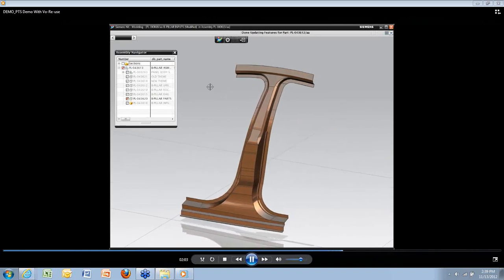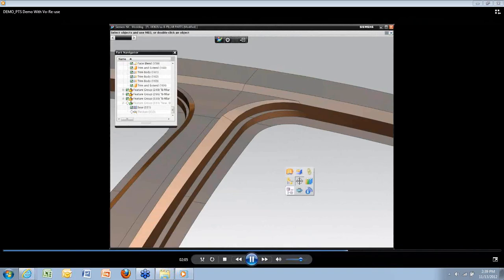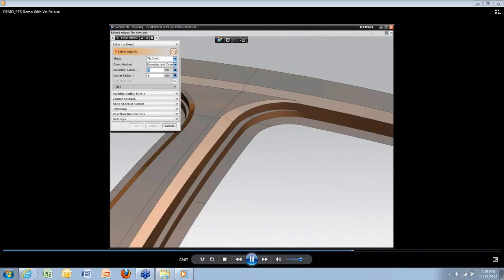Next, we add some conic blends near the top of the B-pillar. The conic blend can transition from a flat surface to the round shape of the blend more gradually than a normal blend with a circular cross-section. Unlike a normal blend, which makes an abrupt transition from flat to whatever radius the blend has, the conic blend increases in curvature according to a parameter called rho, producing a better-looking blend.